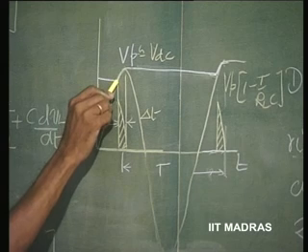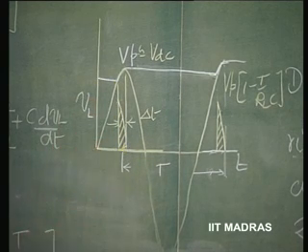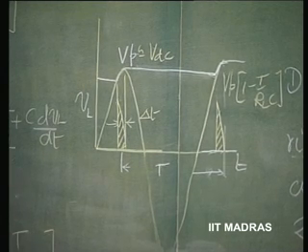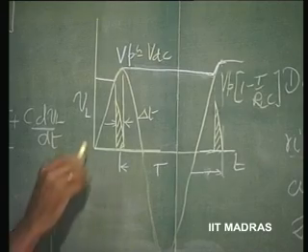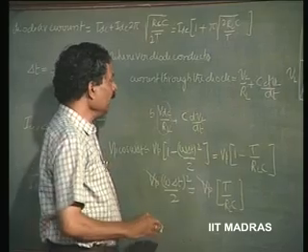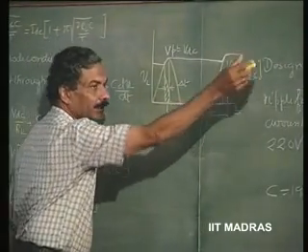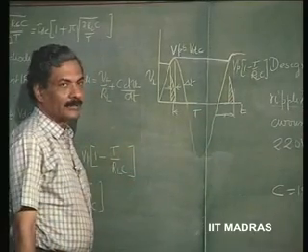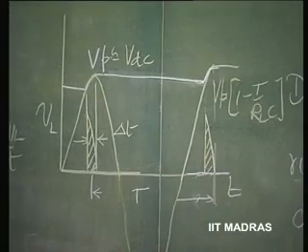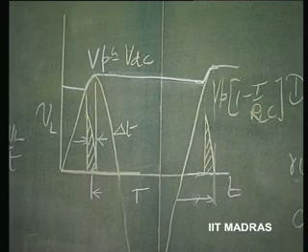Current is maximum at the time of starting of the charge and goes on to 0 as far as the capacitor is concerned, and therefore, the average current at that instant of time is only the DC current that is flowing through the load. So, the DC current plus the capacitive average current is the average current through the diode whenever it is getting connected. This happens every T seconds. Okay? Therefore, it is a periodic rating, that is, a repetitive average current rating for the diode, which is to be specified.